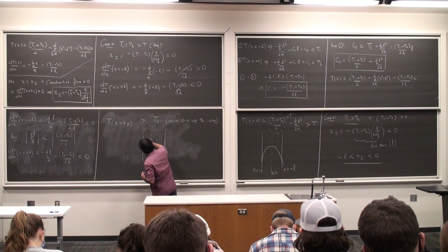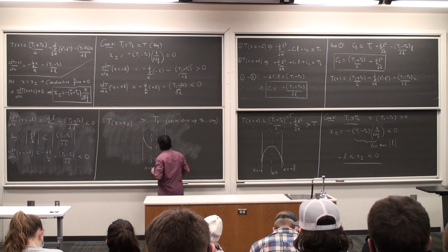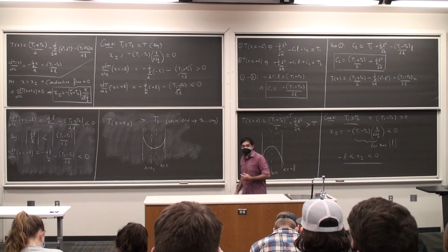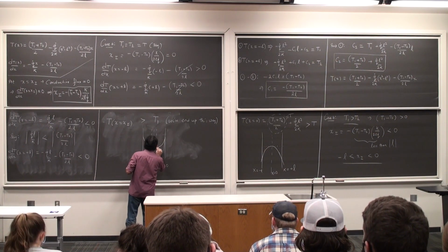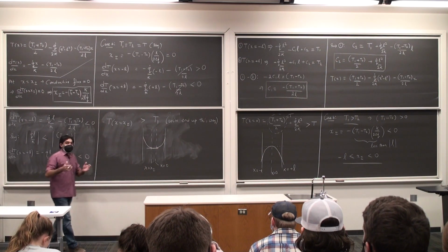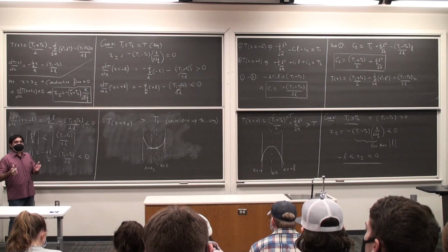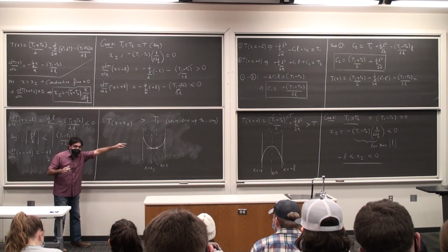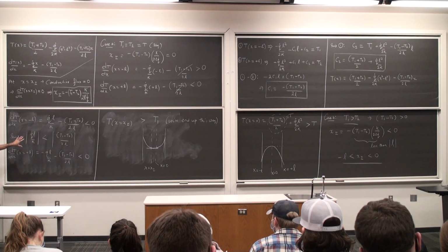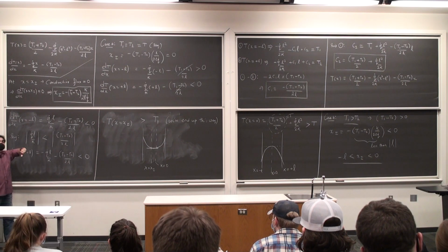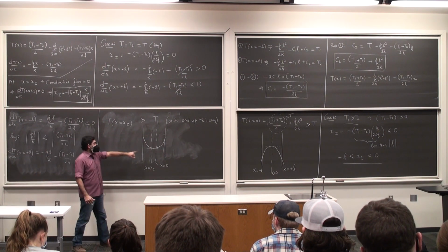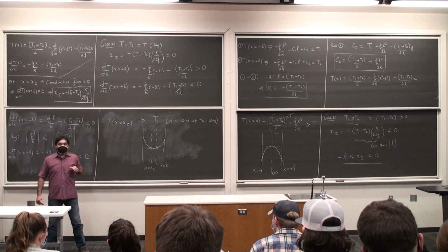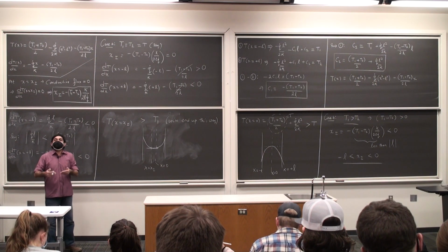So that my profile will look something of that sort, where this is the slope. This cannot happen because if you go through the math, you will find out that the temperature at x is equal to xi, given the range of values that we have assumed for T1 and T2, and this inequality here, it cannot be true. I cannot have a temperature that is higher here, a temperature that's lower than these two, and the heat cannot come in. Okay, so this is unphysical.